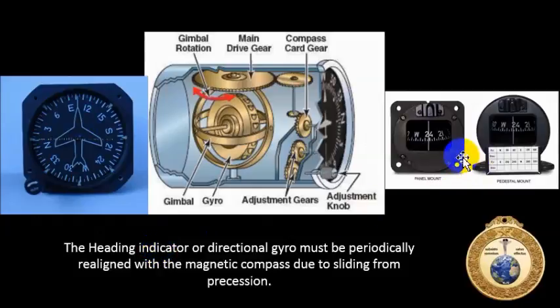When you look at the magnetic compass, it says 240. Hey, I'm looking at 100 degrees. You would just rotate this until what's indicated on the magnetic compass is up top. And then you're good for another 15 minutes, and just periodically check it. Now, this little guy has errors associated with it, and we're going to talk about that.